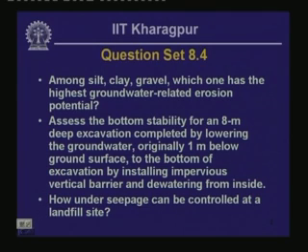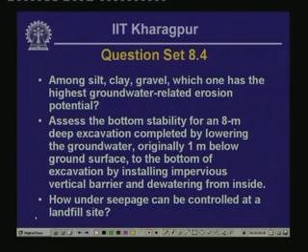The second question that I asked was for you to assess the bottom stability for an 8-meter deep excavation completed by lowering of groundwater, originally 1 meter below the ground surface, to the bottom of excavation by installing an impervious vertical barrier and dewatering from inside. There is a key piece of information missing from this particular statement, that the